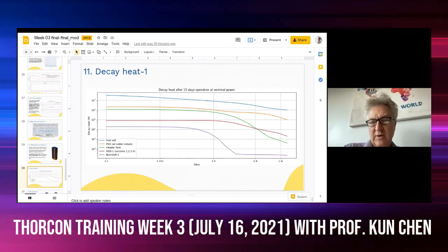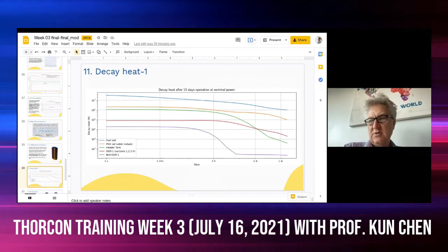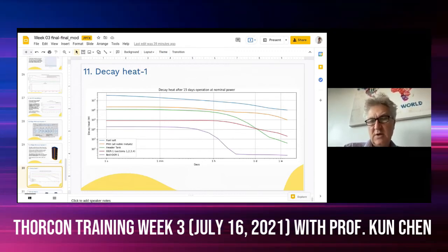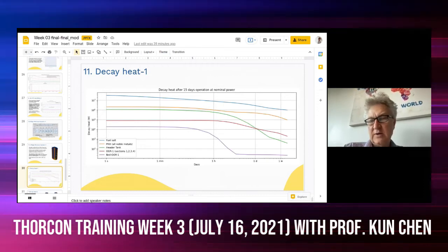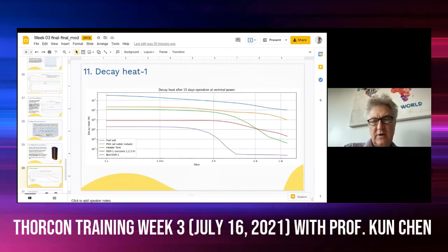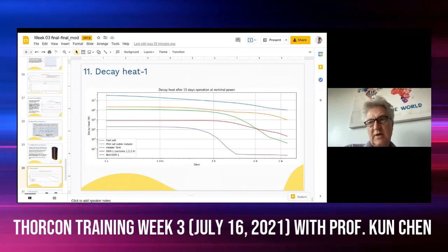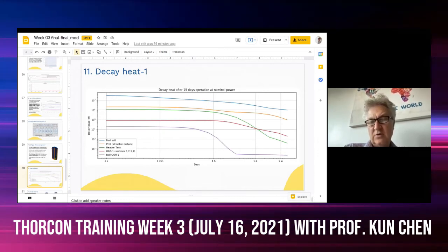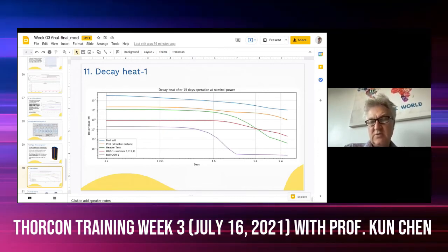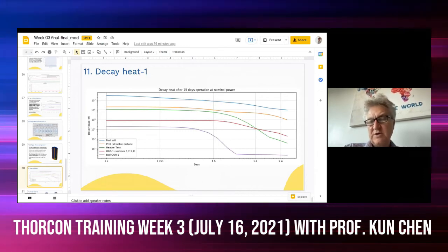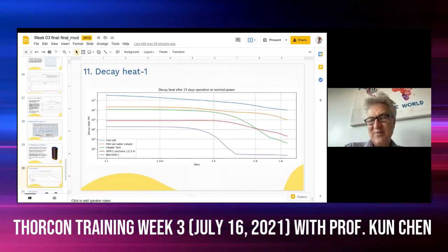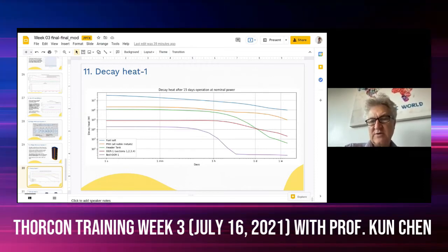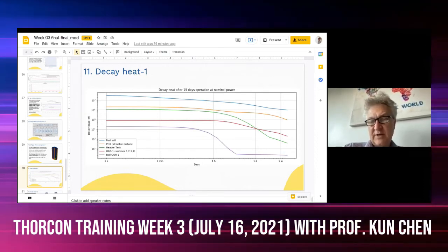The requirement that I see using California's grid is around 0.2% per minute to do load following of the actual load. In California, we have an awful lot of solar, so we get an extreme event between 4 and 6 p.m. when the sun sets at the same time throughout the state. And so there we see ramp rates of about 1% per minute.